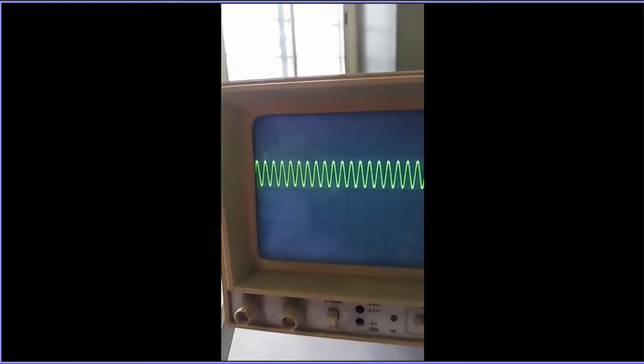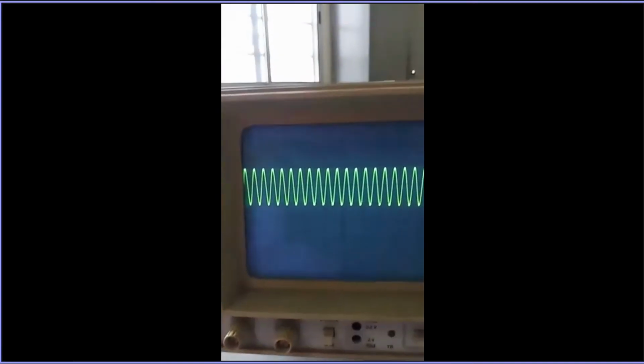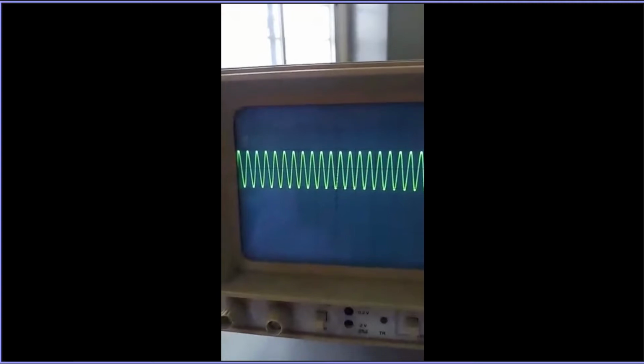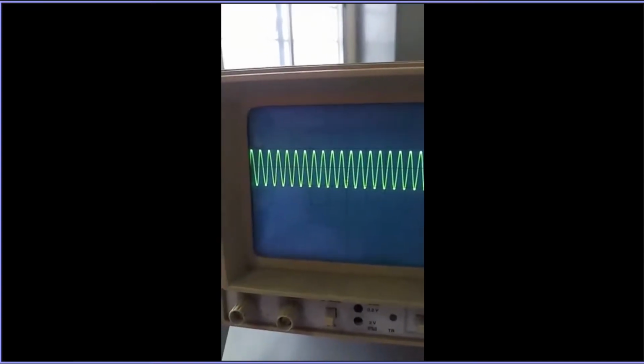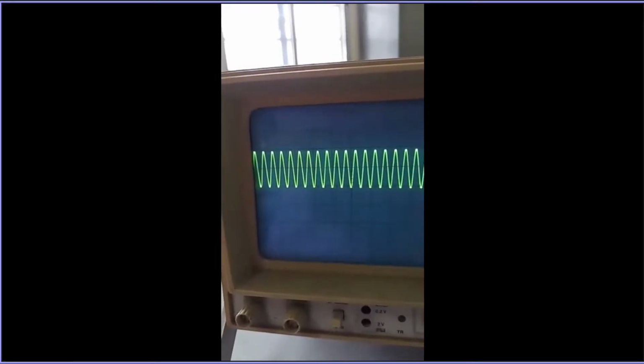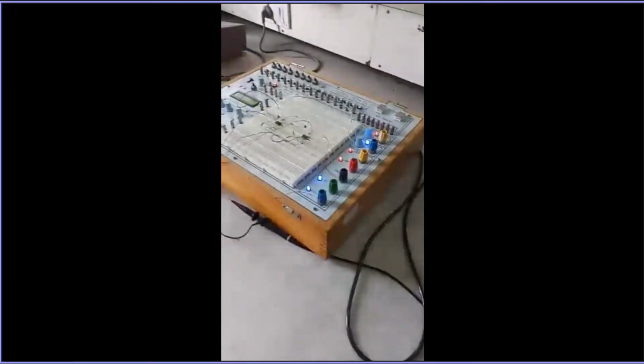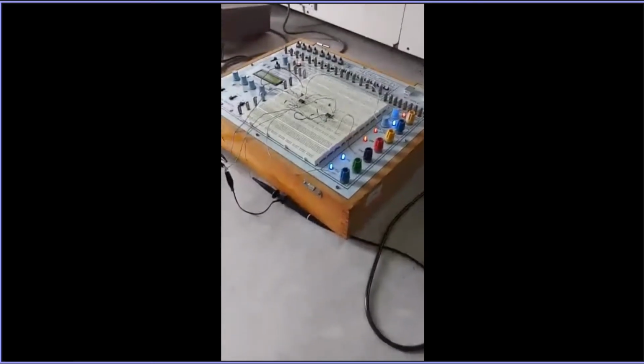Now if we see the fourth order, obviously the deviation will be more. So more deteriorated output. Now it is covering only 2 blocks, right? This is the 10 kilohertz fourth order. So this way we can see the deviation. Okay, after 6.5, the filter does not allow the overall signal to pass, and so we have deterioration in the output, right? So this way we have completed our second and fourth order experiment.